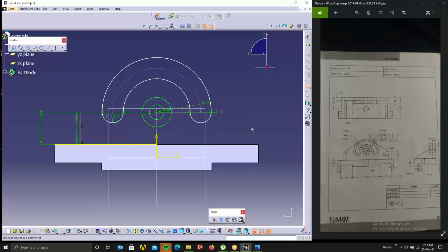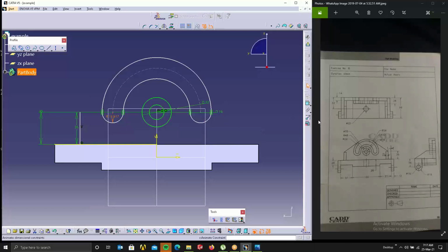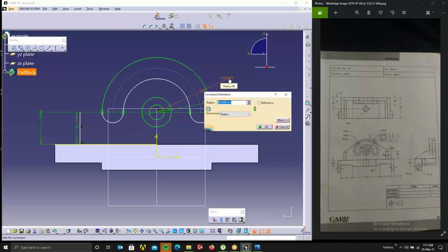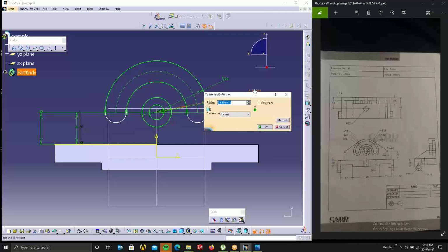This is center. This is also center. We could do that offset. Yeah, offset, but before that we'll just give dimensions. Once the dimension is fixed, then you give the offset. This one's radius is not specified, but the outer radius is specified. So I'll just delete this. Then I'll select this outermost thing. It's 56, enter. And the innermost thing is 24. Sketch 24, enter.